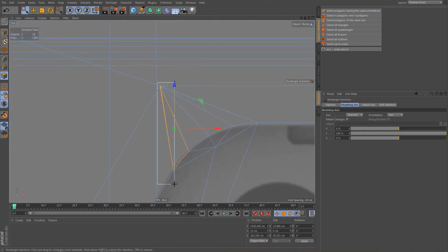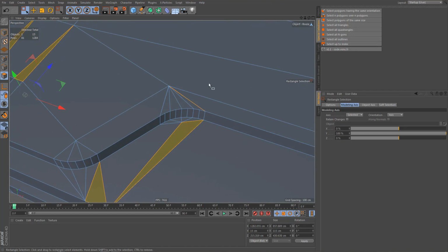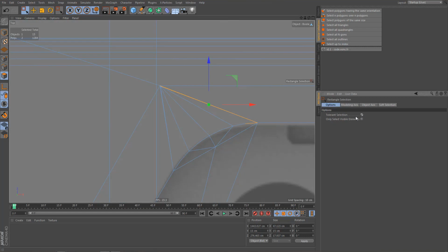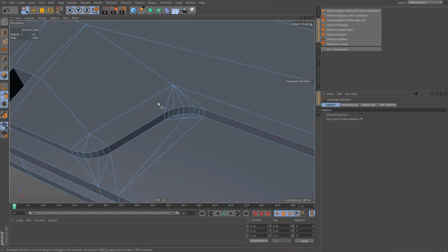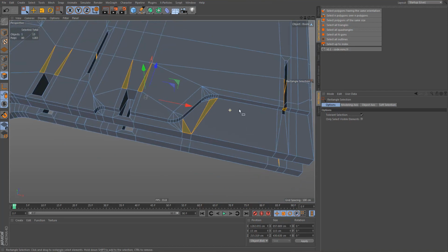Let's go ahead and try and see if we can select this and remove it without causing any issues. Just going to reselect the triangles. Let's try and select this one, and I'll switch on tolerance selection and just deselect this and delete this triangle here. Let's also optimize the object. Select all triangles again.